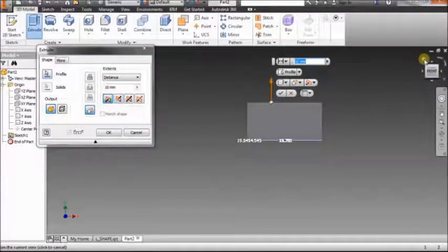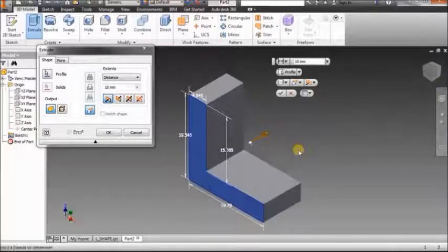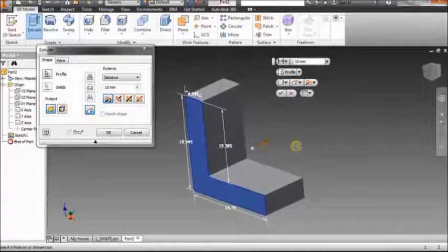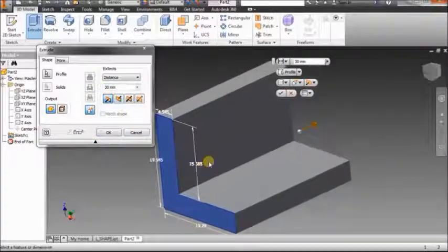So I'm going to extrude that shape. You can always check your Home tab if you want to go back to a basic isometric view. And as I'm extruding this shape, it shows me all the dimensions and all of the corresponding options in the extrude bar, right? Symmetric, asymmetric, flip one side, where the profile is, and then the distance. Once you change that distance, I stuck with 30 millimeters. You can change that later to be something else.